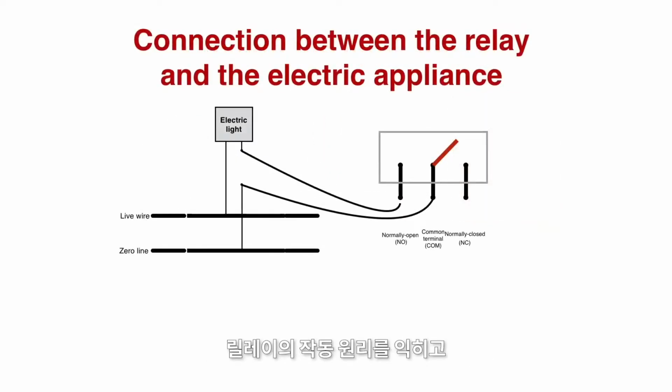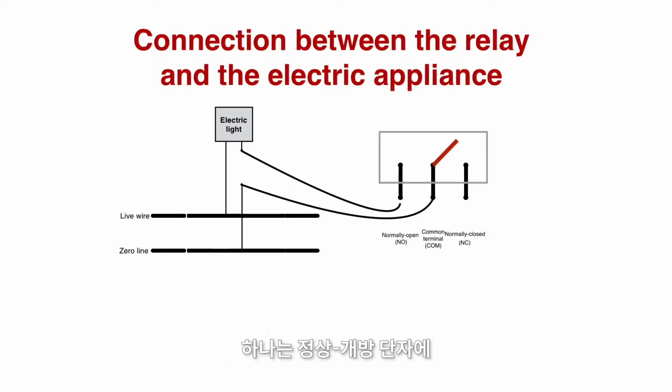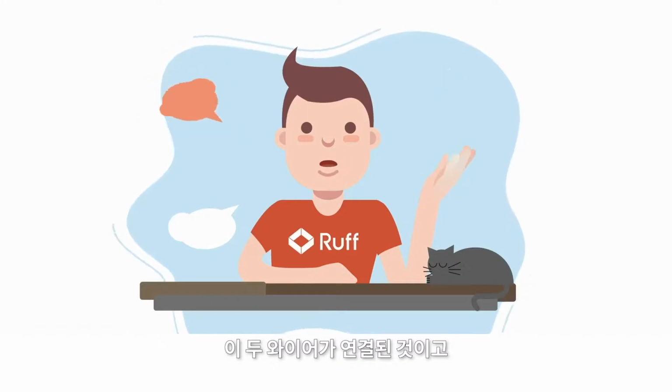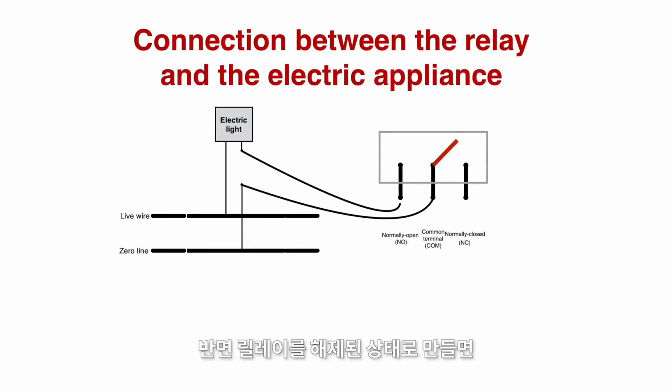After we learn about the relay principle and how to change this light socket, we will connect the 2 wires of light with the relay. Let's connect the 2 wires to the normally open and common terminals of relay, respectively. When we control this relay and it is in the closed status, we actually connect the 2 wires. Upon connection, the light can be properly lit up. When I control this relay to be under a released status, I will short circuit the common terminal and the normally closed terminal. So the 2 light wires are disconnected and the light will be under a closed status.